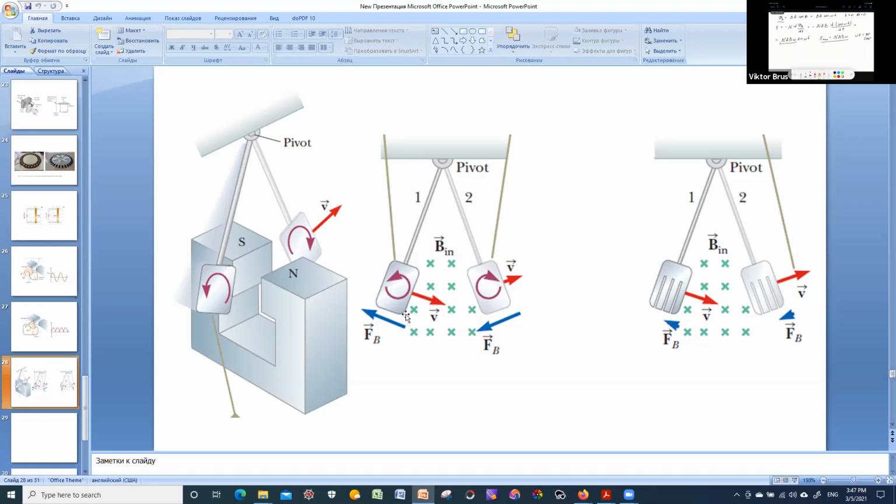So in that case, we prevent forming large current loops, these circulating current loops, and that allows to get smaller magnetic force acting on these moving parts, and that's why with smaller circulating current loops there will be less dissipating of energy by heating these metal plates.